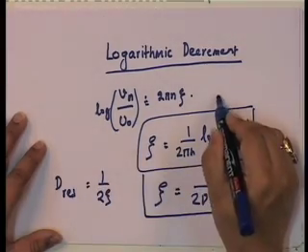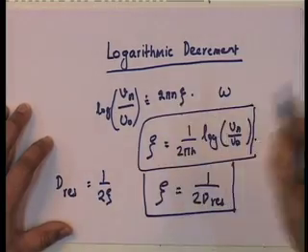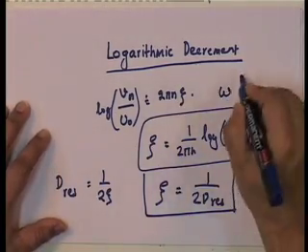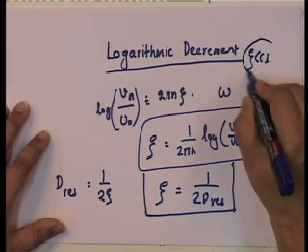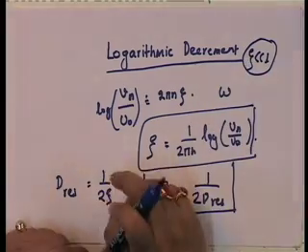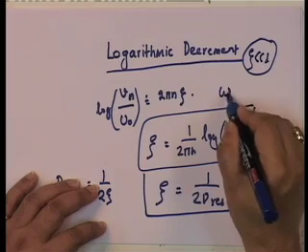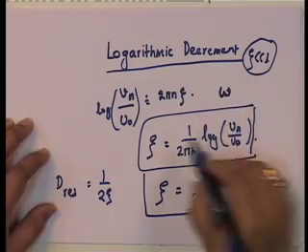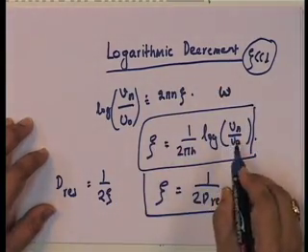We could get omega by looking at the frequency of the free vibration, because all of this is valid when xi is very much less than 1, which is what it is in real structures. That is why you would get omega d, but omega d is really the same as omega if xi is less than 1. So we can get omega from the free vibration, and xi from the logarithmic decrement.